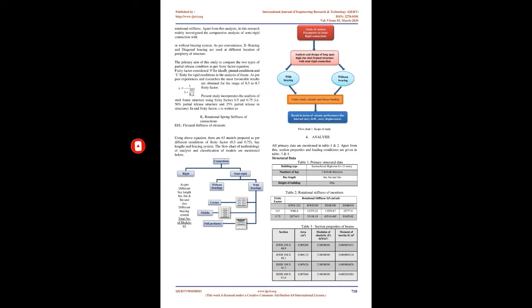Generally, connections are characterized in two types: 1. Moment connections and 2. Pinned connections. Besides that, in actual practice steel connections are not ideally rigid or pinned, but the behavior of connections falls between these two conditions, called semi-rigid connections, which are based on their stiffness criteria.